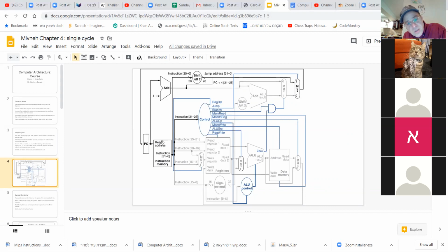There's this instruction memory. This is access to the 4 gigabytes of memory. And he's pulling out a particular instruction and shoving it into these lines. Now I'm asking myself, well, do we need a register there to store it? Let's think about that. Why would we need a register there? Let's just pull it out and immediately stick the output onto these different lines. We don't need a register.